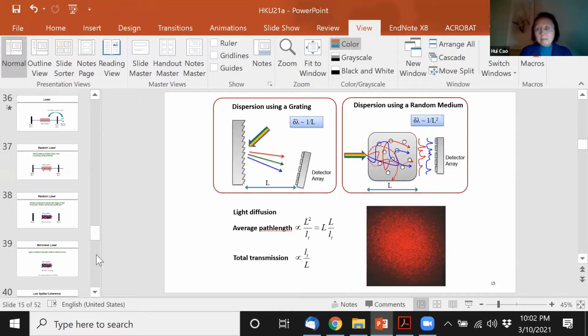Let me give you one example. For example, for photolithography, right? People use excimer lasers, which have a very narrow bandwidth. That's a very high temporal coherence. So for single wavelengths, if I want to get rid of the speckle noise, I can only play with the number of spatial modes, not the number of spectral modes, because my laser is just very narrow.